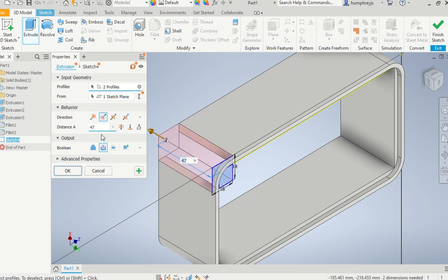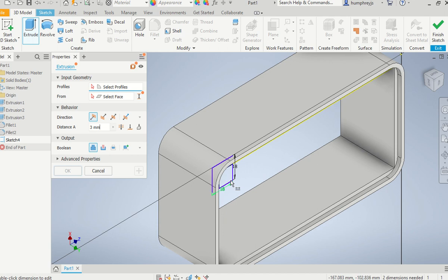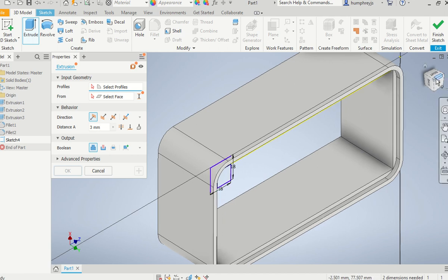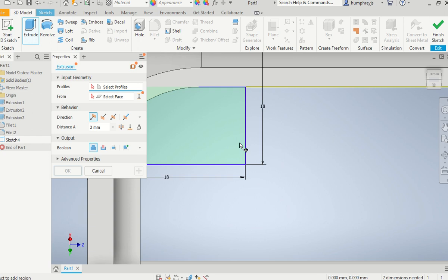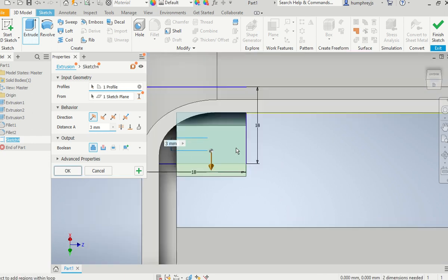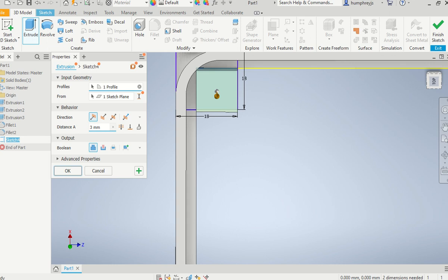Now, if I select the whole of that square, it's of course going the other way. That's negatively extruded now. Can you see? You want to positively extrude. Can you see my corner become square again? So I'm not going to select all of it. I'm just going to select this part here. So extrude. That's it there. Can you see? I've got it. Sometimes it's quite hard to select, but what I've done there is just selected